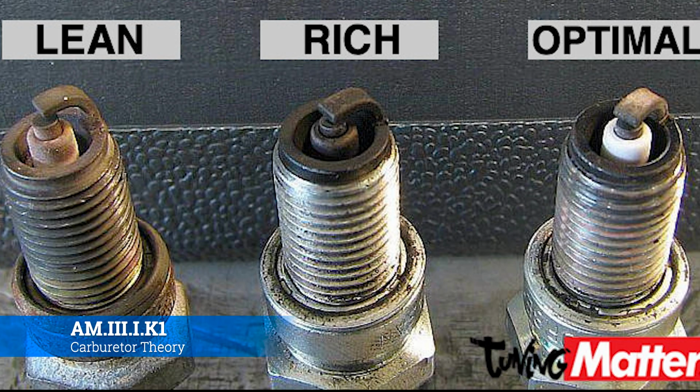Okay, so what happens if it's too rich? Too rich would simply mean that you are not burning all of the fuel that's available. The engine's only going to burn for so long. This cycle only goes for so long, and there's only so much air in the chamber, so it could burn, and then you're going to have a bunch of leftover fuel that just wasn't combusted entirely. And just like with any other fire, leftover material turns into soot, ash, or residue of some variety.